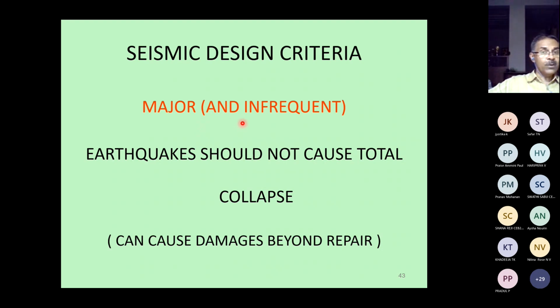And it may not even happen during that time, because on the design side, we take once in 500 years as the maximum peak earthquake, the maximum considered earthquake, or MCE, as it is otherwise called in design. And this 500-year repeating earthquake need not fall in the 100-year lifetime of our structure. Our normal structural life we take as 100 years, for any building or normal bridges. Of course, special structures are designed for a much larger life, like 150 years or 500 years.